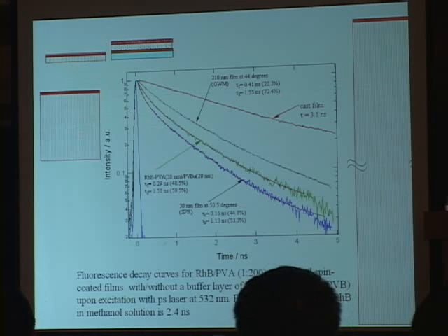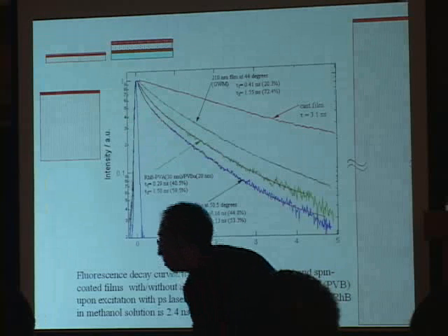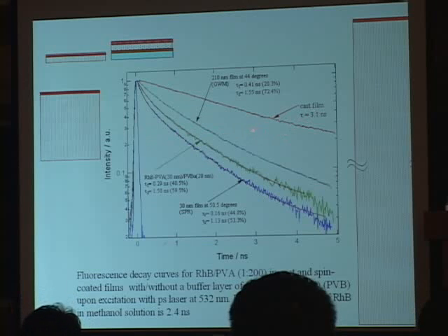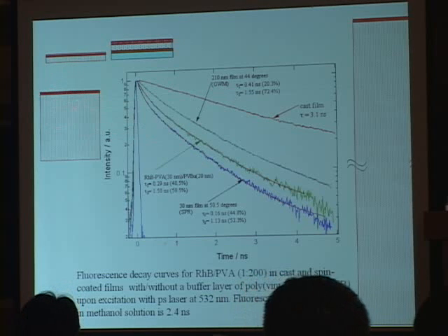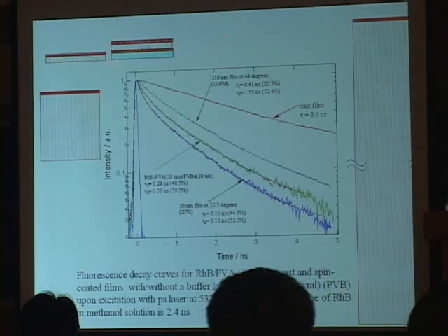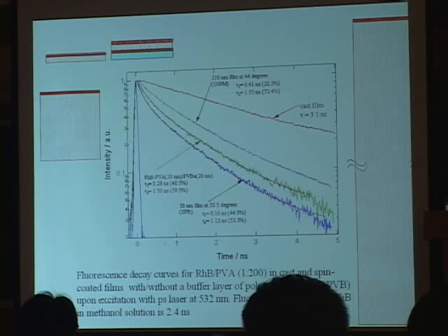Depending on the thickness, the molecular motion changes dramatically. By decreasing the thickness, the molecular motion becomes very, very rapid, as shown here. This is a fluorescence decay curve, from which we can get information on the mobility of the polymer chain in these areas. So we are now analyzing using a two-phase model, or in some cases a three-phase model: surface, bulk, and interface. All these areas show different thermal properties.